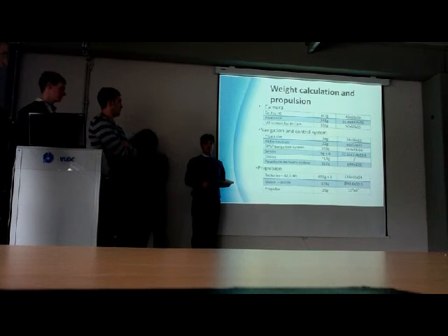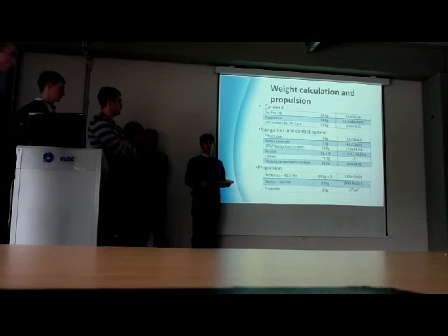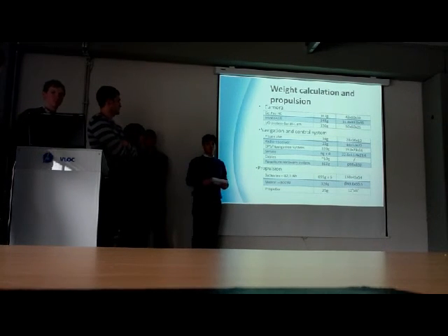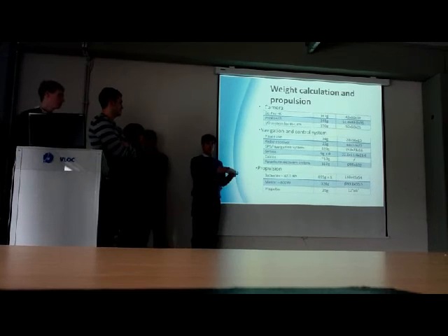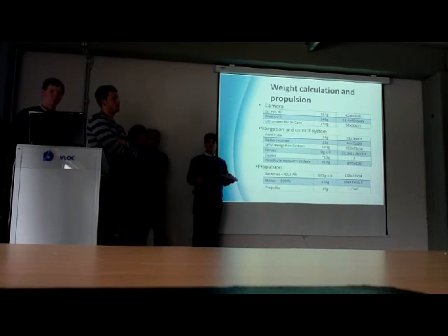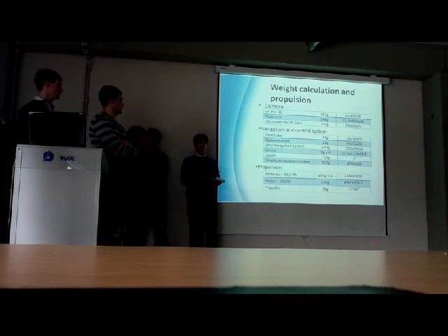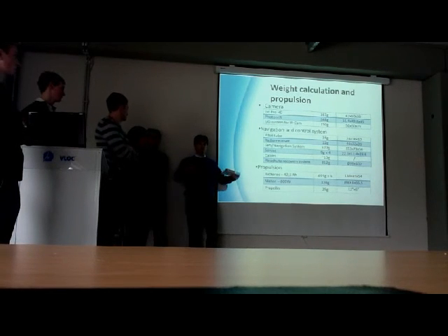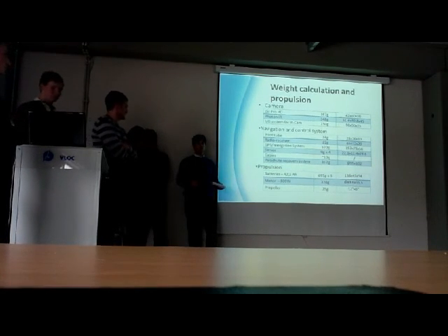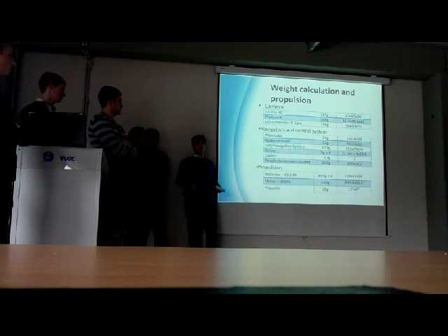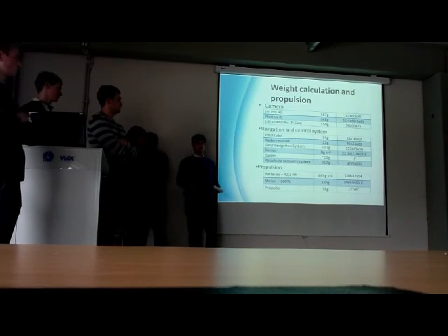An electroactive polymer can do an attraction force of 15 Newton. So at low Reynolds number, you will not have to move 15 Newton on your control surface. So we estimate to have 40 Newtons for all the moving parts, so we can do 40 Newtons divided by 15 Newtons to obtain the number of wires that we need.